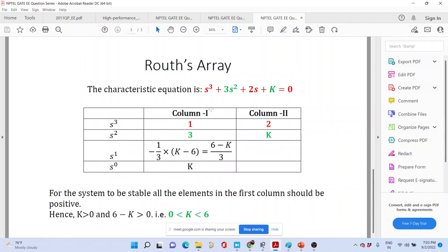Okay, so it is simple, everything is okay, but let me ask you a few questions from here to get a better insight. Anubhav, you have solved this sum, right? Yes, sir. So tell me, this Routh array can tell me everything about the stability of the system, right? To determine the stability, what we need to know is that all the closed loop poles lie on the left-hand side of the S-plane. We do not need to know the exact location of the poles. This much information is enough for us, right?